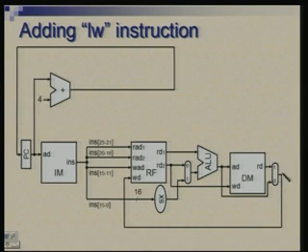When you give control as 1, it will send this to the register file, and when the control is 0, it sends this to the register file. So, we will have to remember that for add, subtract, and or instruction, the control has to be 0, and for load instruction, control has to be 1 here. Okay. So, this is one part of the picture.